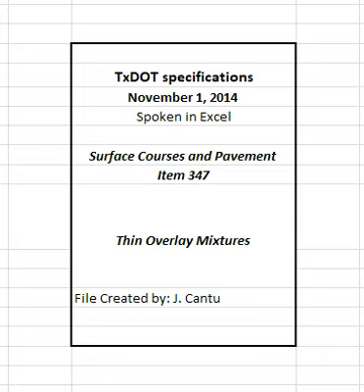Obtain and provide approximately 50 pounds of trial batch mixture in sealed containers, boxes, or bags labeled with the CSJ, mixture type, lot, and sublot number for the overlay test. The engineer will be allowed 10 working days to provide the contractor with Hamburg wheel test and overlay test results on the trial batch. Provide the engineer with a copy of the trial batch test results.